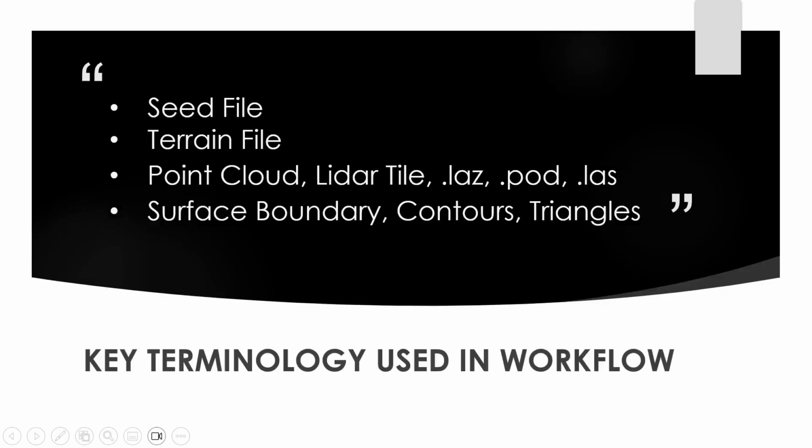Some of the terminology that we're going to use today is seed file. You need to know that we're going to have to use a 3D seed file to import a proper terrain. We're also going to use the term terrain file. Terrain file and LiDAR often get used synonymously, but truly what we're doing is making a terrain out of the LiDAR, so they're actually not the same. We're also going to be talking about point clouds, the LiDAR tile, .laz, .pod, and .las files.